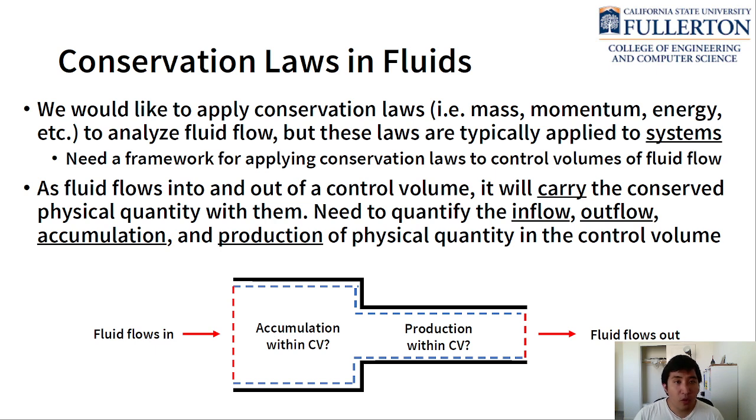The whole idea behind Reynolds Transport Theorem is that it's a mathematical expression of a very basic idea: as fluid flows into and out of a control volume, it's going to carry physical quantities with it. So when fluid goes into a control volume, it carries its mass with it, and when the fluid flows out of the control volume, it carries its mass out of it. So we have mass coming in, mass coming out. We basically need a way to mathematically quantify inflow, outflow, accumulation, and production of a physical quantity within a control volume.